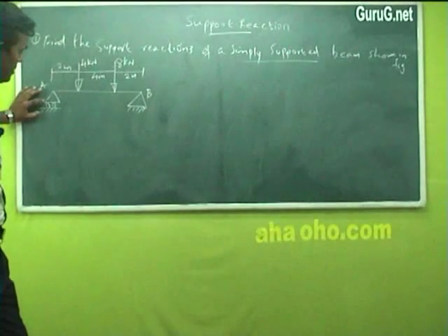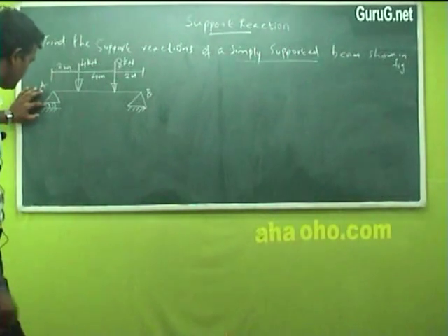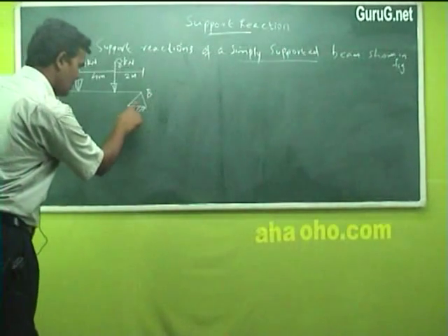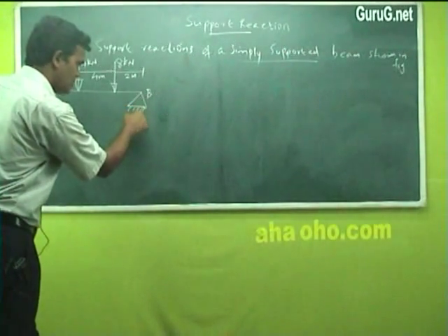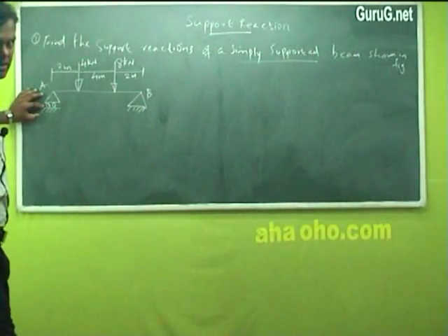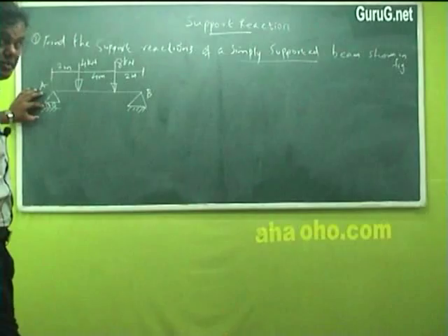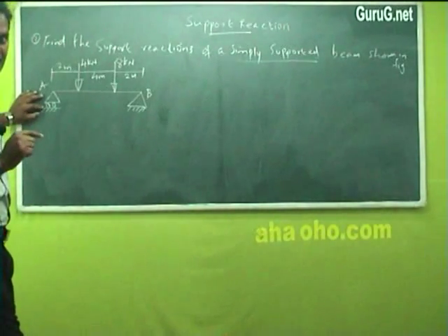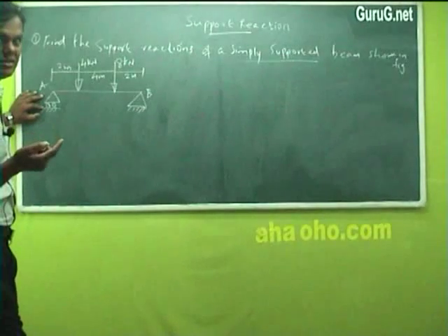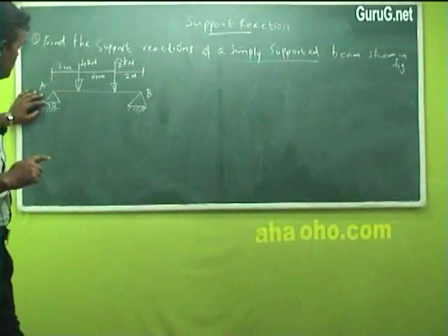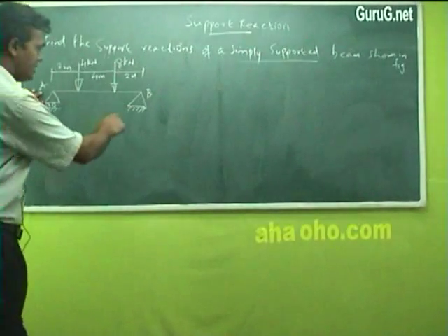It's a roller support. This sketch indicates that if there is a roller like this, it's a roller support. And this one, without the roller, with this kind of marking, indicates a hinged support. So it's very important to identify what type of support it is. Only then can we write down what the reaction is, and how many types of reactions there are. That depends on the type of support. So here it is a roller support, and this is the hinge support.